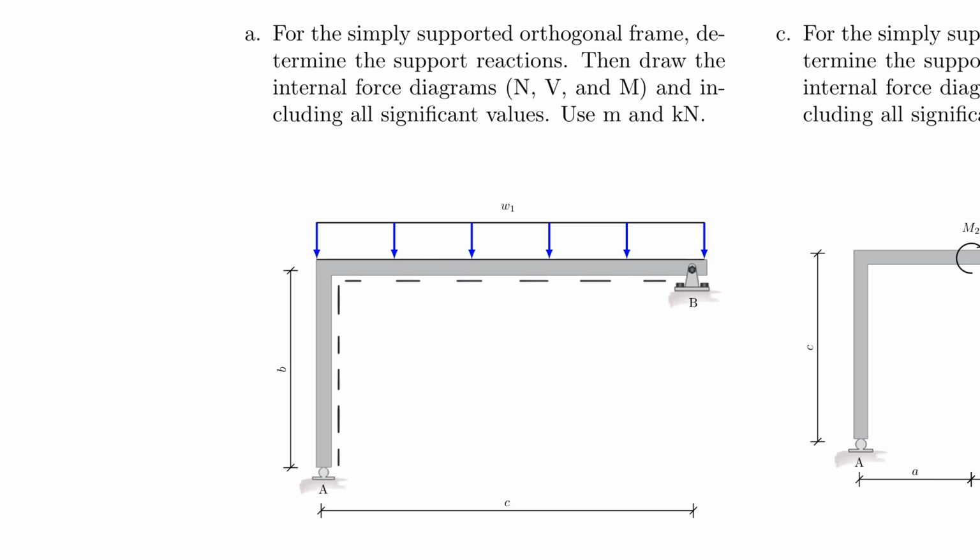or at least they appear to be different. Of course, physically, it doesn't change, right? You cannot differentiate the system physically by drawing the fiber on the other side. Physically, everything has to still be true. So this is just a trick we use as engineers for better communication. You need to communicate where the bending moment is positive and where it is negative, so that later on engineers actually know, for example, where to put the reinforcement steel and so on. You will learn this in later classes, but it is very important that you identify where the positive and the negative direction is.